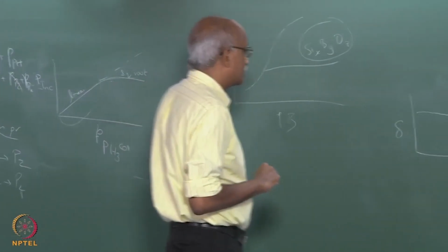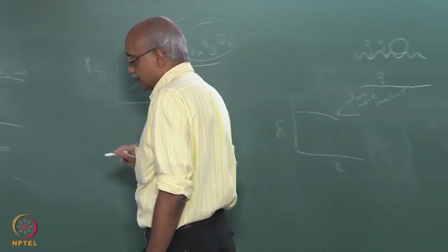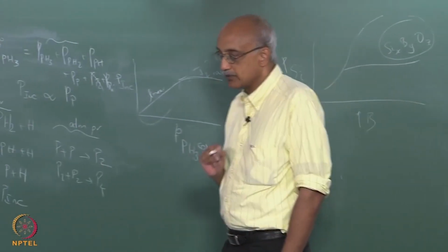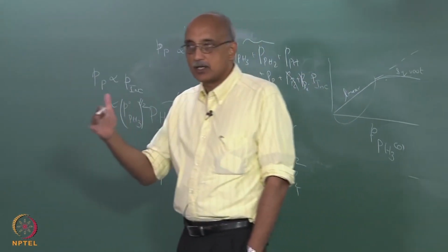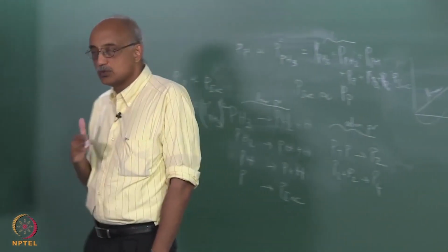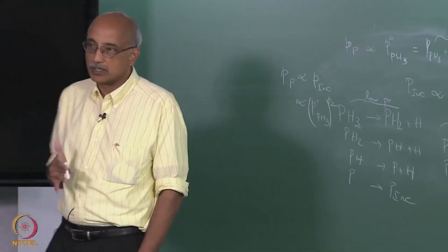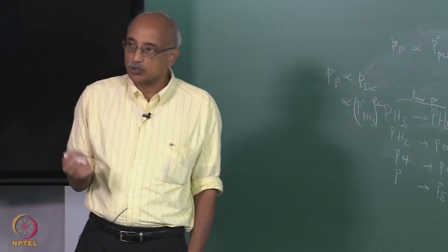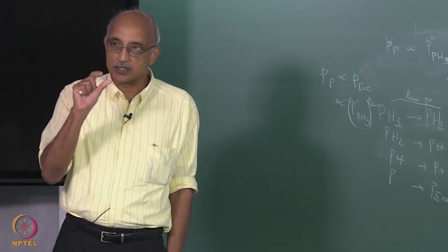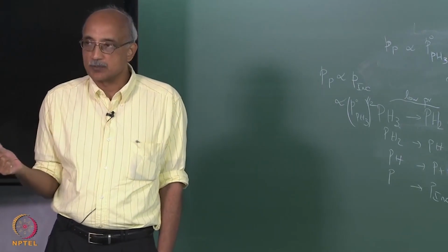The other interesting thing when we talk about the use of dopants in a CVD film is that it is a layer by layer effect, which you can use to your advantage for the most part. You can turn on the dopant for some period of time, so that the dopant is incorporated in a certain thickness, and then turn off the dopant supply.